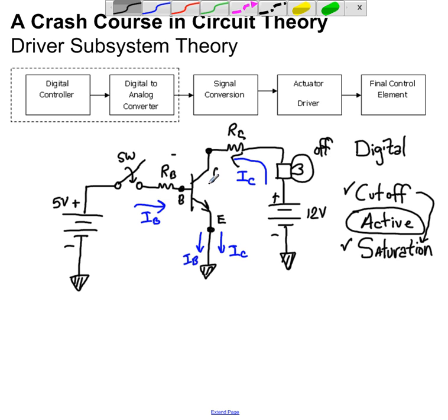If you look up the word saturation, it basically means it cannot hold enough. There's too much. So it has saturated. It cannot hold any more. So it is at its limit. However, the transistor is still good. It's just not acting in the normal capacity of a current gain device. So we can use this to act as a closed switch.